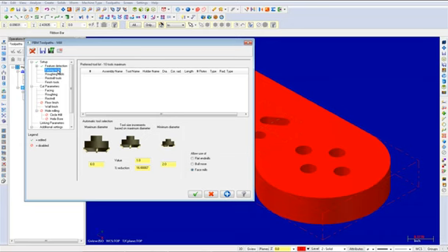This is where you set up the tools for a facing operation. You will not be setting up a facing toolpath for this part. I will explain a few of these parameters. Preferred tool list is where Mastercam searches your preferred tools list for the largest to smallest tool to find an appropriate tool for each FBM generated toolpath.